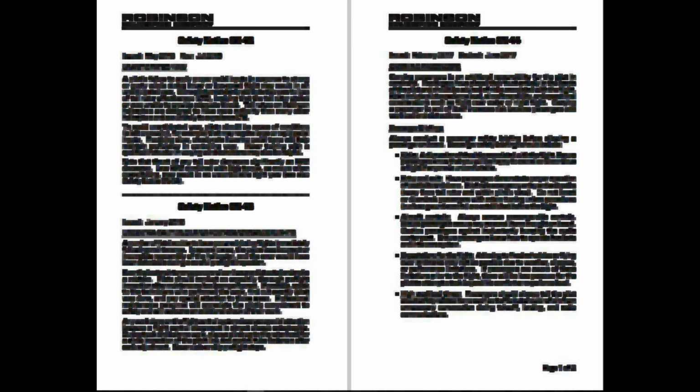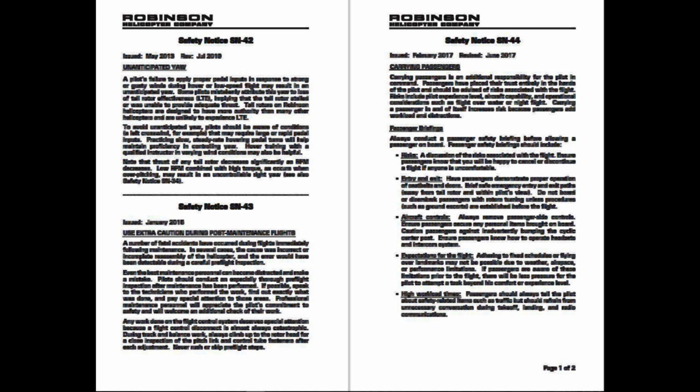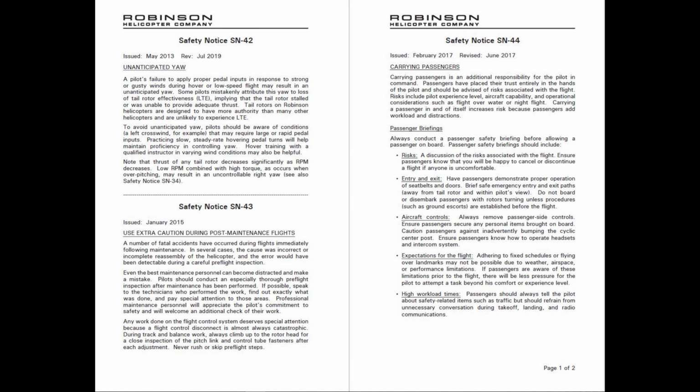What should the pilot do if the aircraft just came out of maintenance after having its belt drive system worked on? They should verify a maximum of 1.5-inch deflection before flight. While running up, verify that the rotor turns within 5 seconds after engaging the clutch switch.